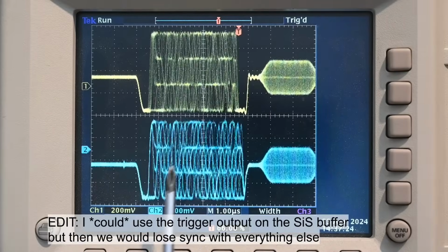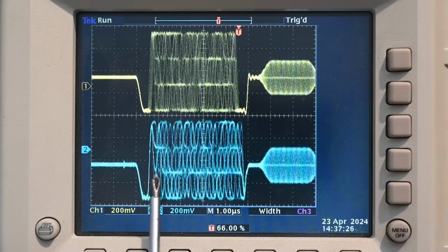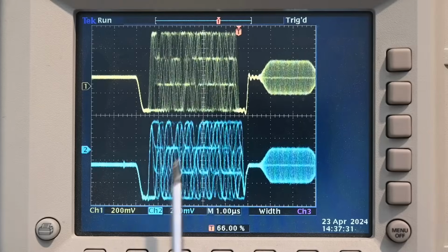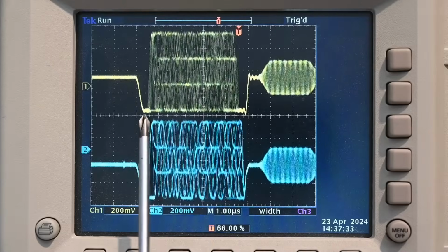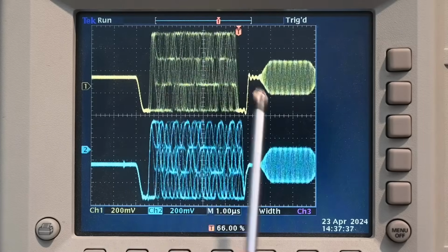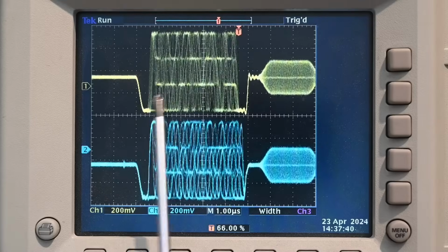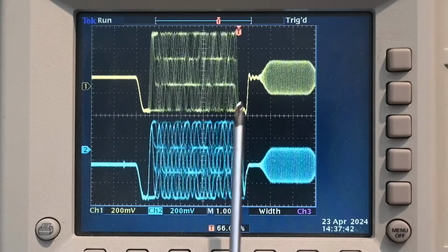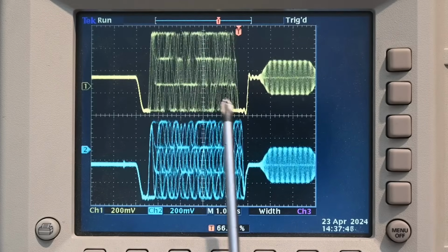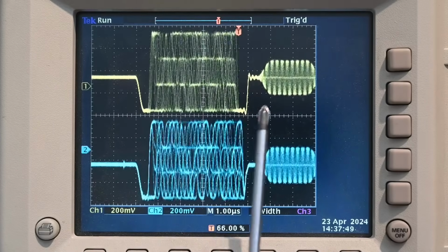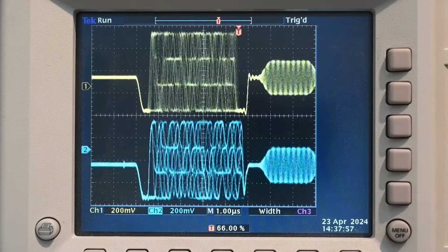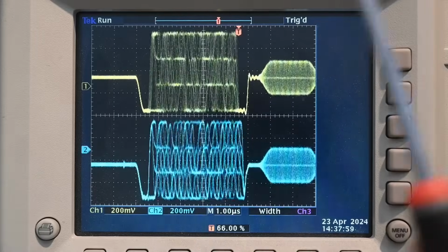Now when we come back to the BBC burst, we can see another difference here, and that's that more of the sync period is occupied with this burst, whereas RE Technology have used noticeably less of it. And this is also quite interesting. So they were quite a bit more ambitious with how they actually coded the data. They're squeezing it into a shorter space of time. And this potentially may make the system less robust. This is why I'd really love to find a decoder for this, so we can actually check whether or not that's the case.